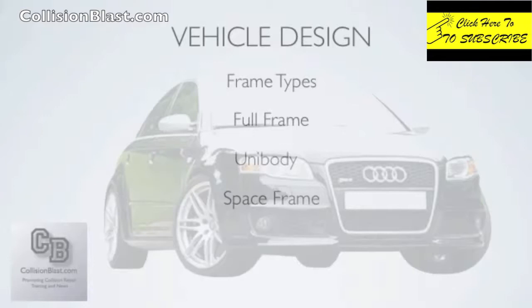But what a full frame is, is where it's two pieces. You've got the frame, and then you've got the body that bolts onto the frame. It's two pieces. Now, there are some unitized bodies that are one piece that bolt onto the frame, so it's like having a unitized body that is one piece that bolts to the frame. On a full frame, the suspension, the engine, transmission, everything bolts to the frame. So you could take the body off, or all the body panels, and all your mechanical parts would still be bolted onto the full frame.